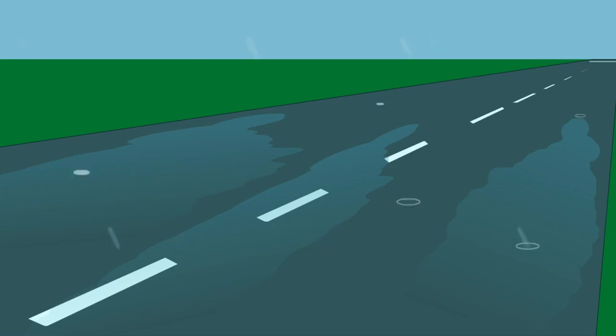A wet runway is one that is covered with water, or equivalent, to a depth less than that defined as contaminated, or has enough moisture on the surface to give it a reflective appearance, but without significant standing water. There are a few other terms used in connection with precipitation on runways. A damp runway is one that is not dry, but does not have a shiny appearance.